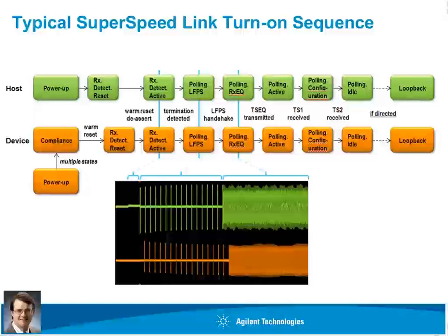Receiver testing runs through the same channel topology, but is quite a bit different in the mechanisms to get into the test modes. So the main mechanism you need to support and be able to get into to support receiver testing is loopback mode. Loopback is a condition of a device transceiver state where every pattern sent into the device receiver will be sent back out the transmitter.